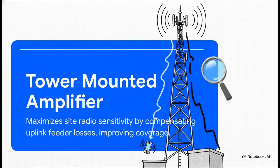Next up, we have the TMA, or Tower-Mounted Amplifier. And let me tell you, this piece of hardware is an absolute lifesaver for cell coverage. It maximizes the site's radio sensitivity by compensating for uplink feeder losses. I mean, think about the weak signal coming from your tiny mobile phone trying to yell at a tower miles away. By reducing the base transceiver station noise figure, the TMA dramatically improves overall sensitivity. It amplifies your weak signal right up at the top of the mast before it has to travel all the way down those long cables to the base station.